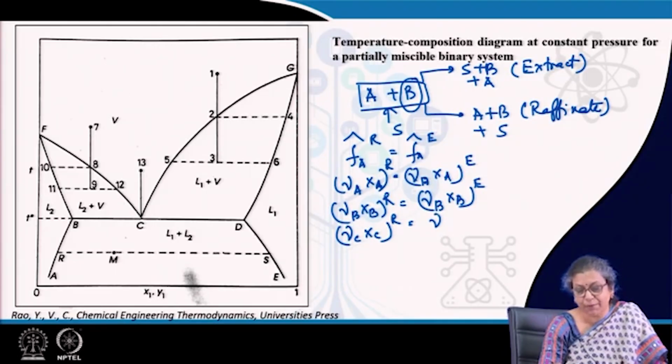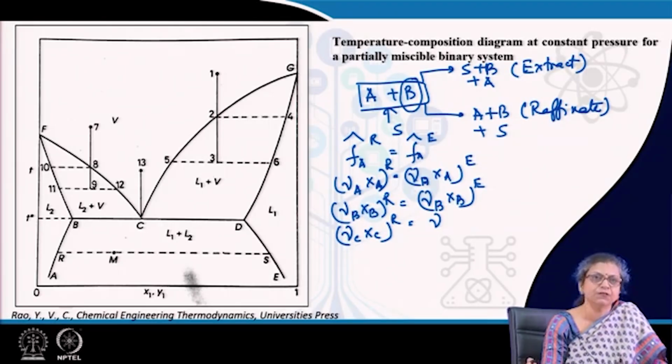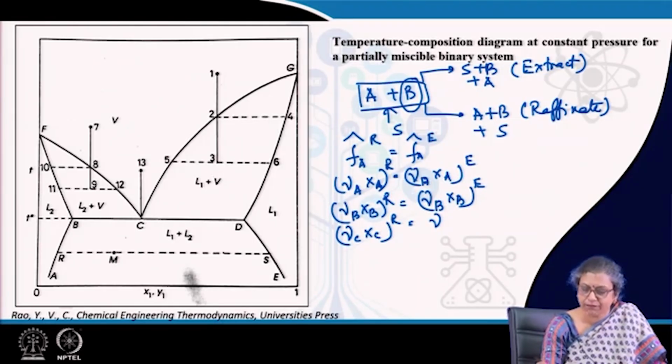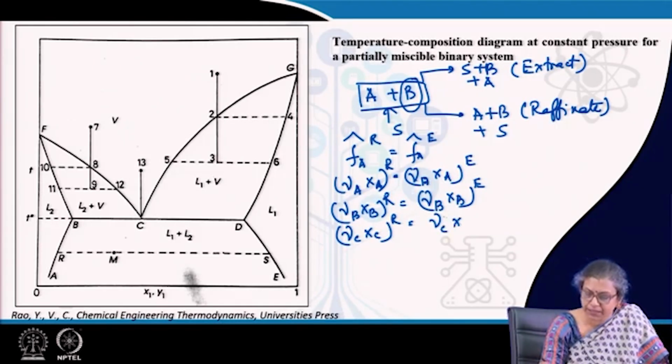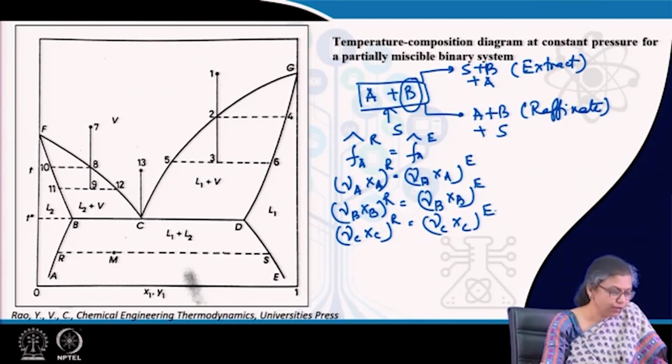So, therefore, gammas are extremely important in this particular case. The process of finding gammas is the same, but in most cases we have to include the gammas in the phase equilibrium equations written down for liquid extraction cases.